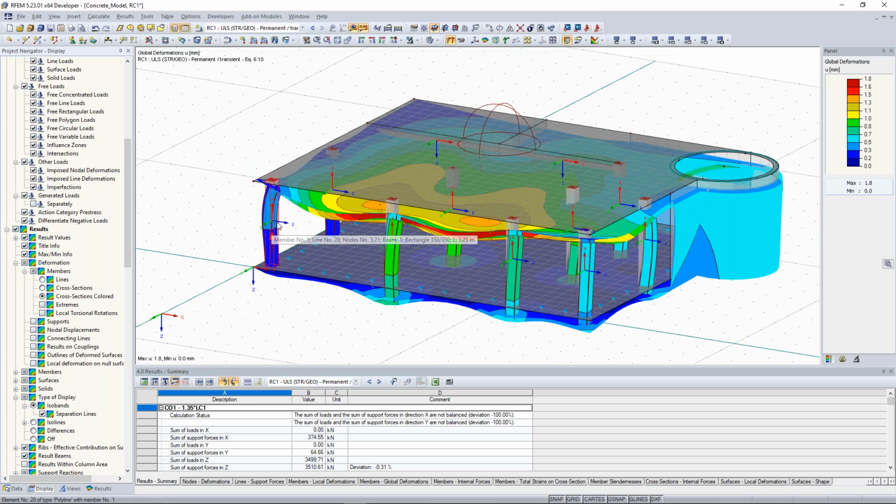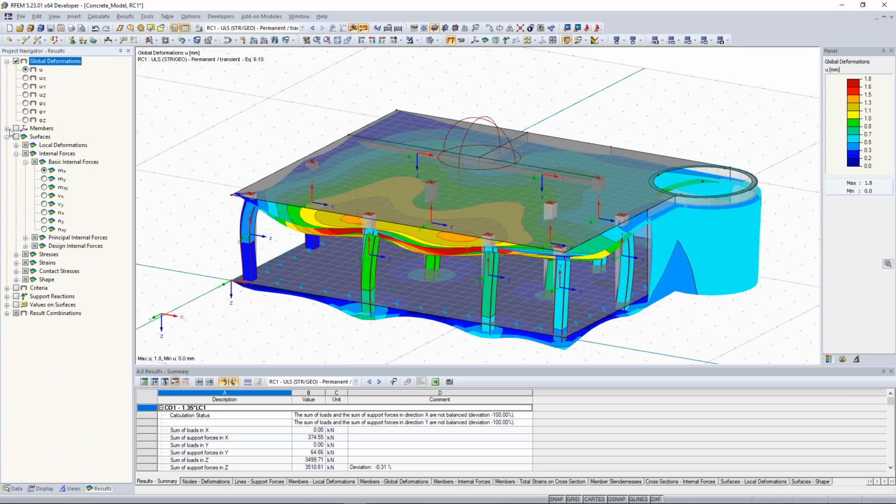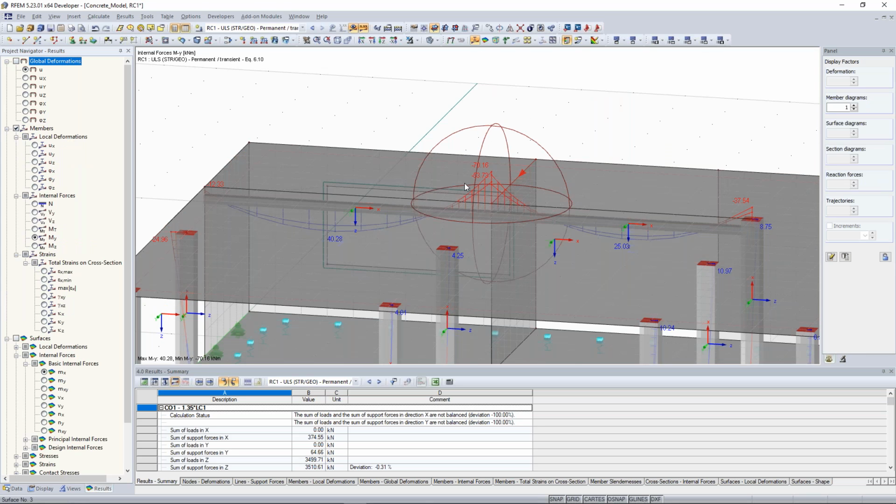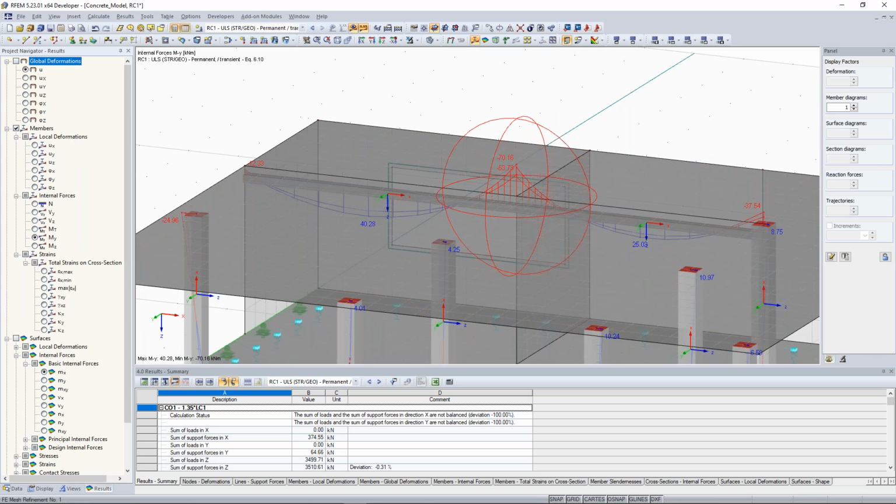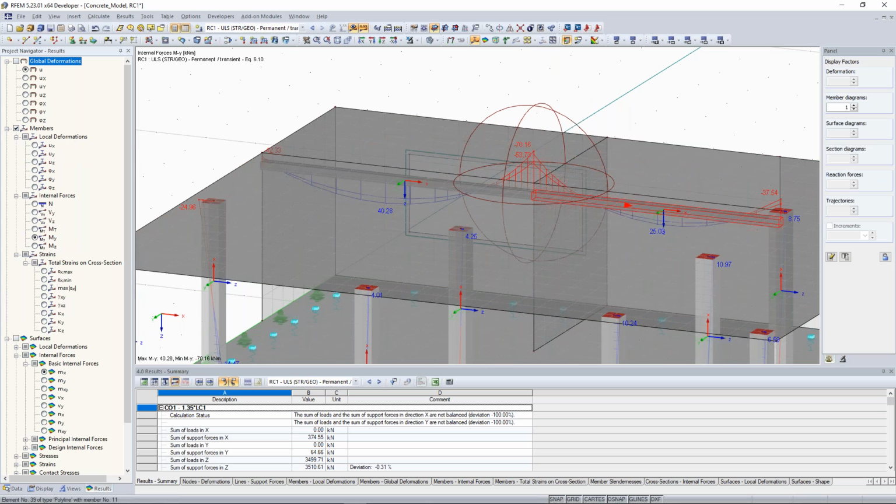Okay, good. Next thing, members, the internal forces. Let's go to the downstem beam and compare the results. Okay, these results look very good. So we have here field moments. Also here this negative moment over this wall. I think by the plausibility check, this is okay.